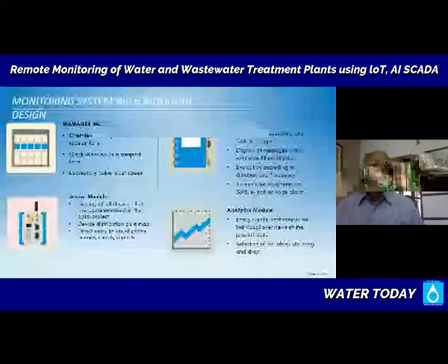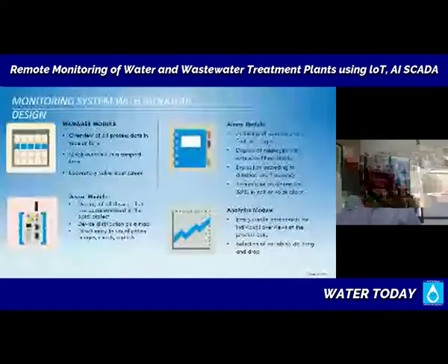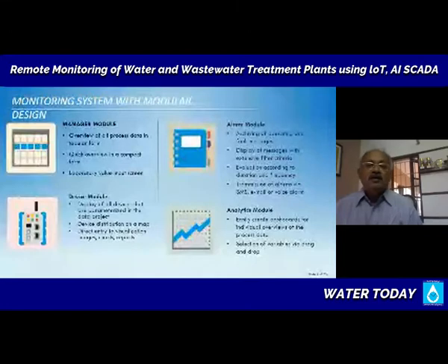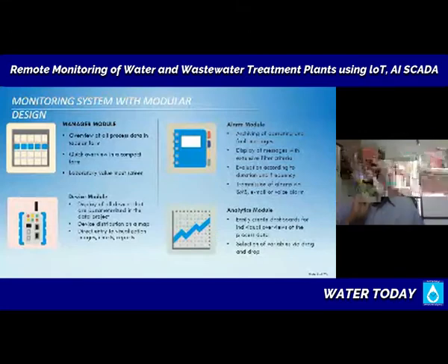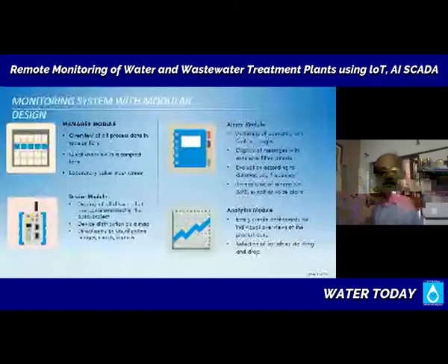And then you have abnormal conditions in any water network operation. Like you can have low pressure, you can have high flow, you can have low level in a storage tank, or a very high level and overflow from a storage tank. All of these are alarm considerations which tell us to go and do something. When something is not right, then you have got to go and maintain. So you have the alarm capability, and then very importantly, the analytics module.